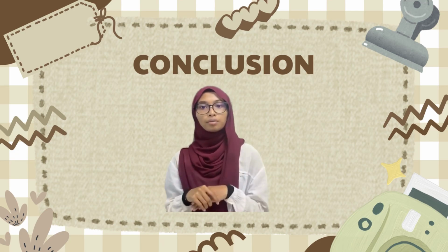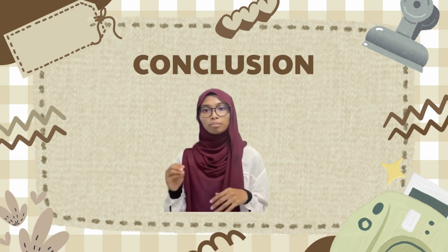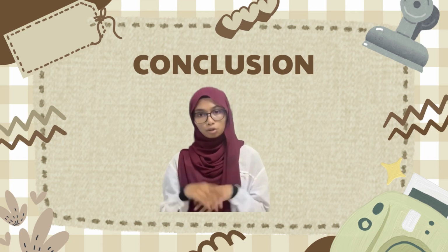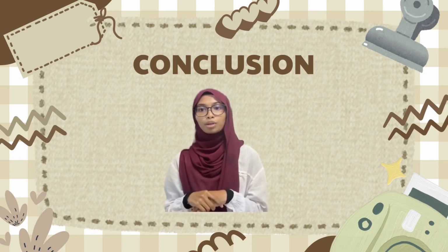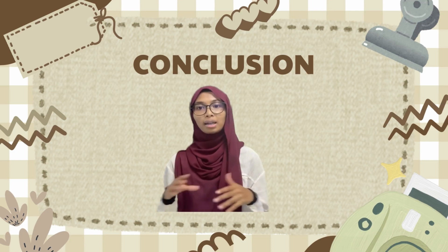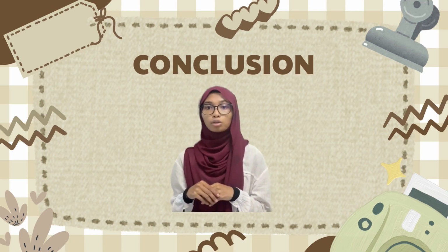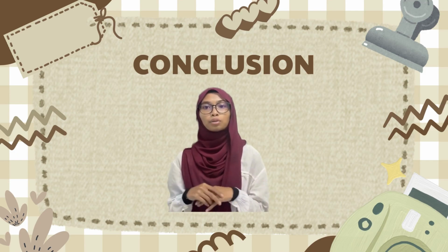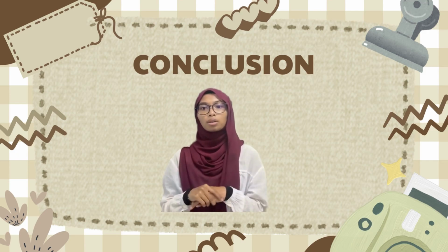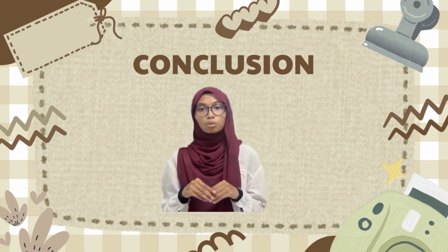For instance, the differentiator had to be modified with an extra capacitor to limit high frequency gain and ensure stability. This experiment taught us a valuable lesson about compromise in analog electronics. In order to ensure that the circuit is stable and useful, designing a successful circuit requires using fundamental concepts to overcome the limitations and defects of real-world components.